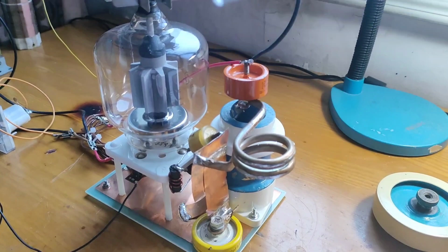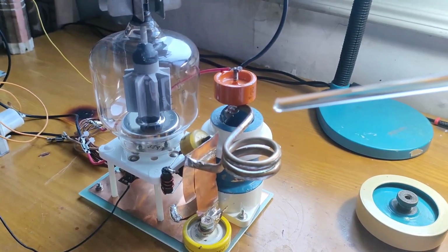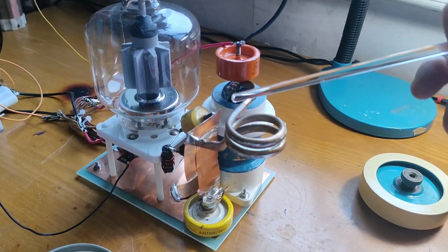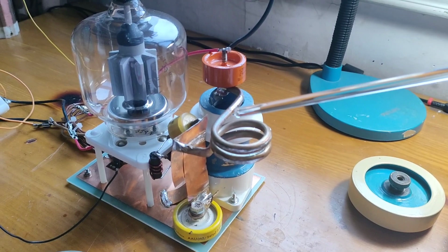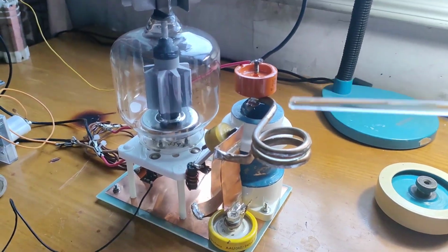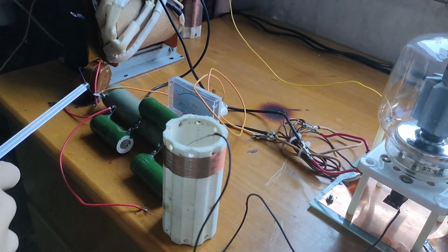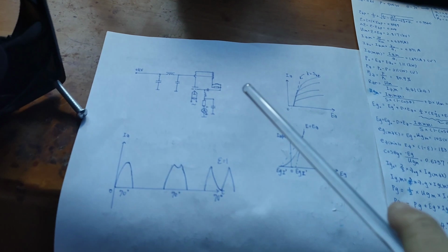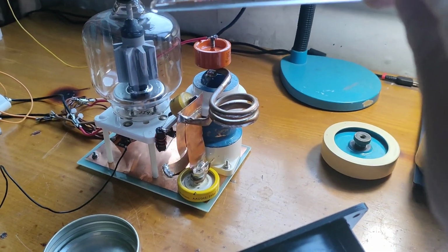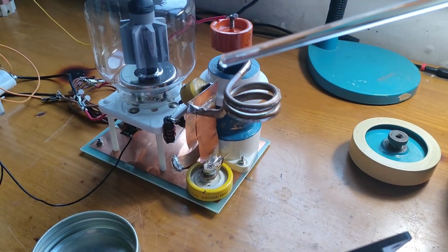First, you power it up, but at a lower anode voltage than you designed, and use some neon discharge lamps or some ampouled gas, which can be put close to the anode or the resonant coil to see if the oscillation has started. And if the oscillation has not started, you can just move the grid leakage capacitor, which is here, and that will give your tube a lower grid negative bias for a better start of the oscillation.